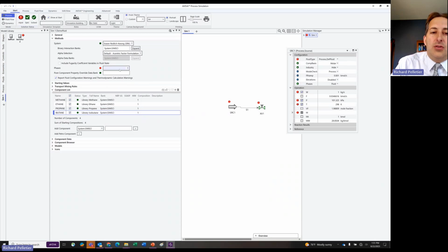So you have to be careful what you pick, to make sure that it is all encompassing of what you might have within your system. For these more complex ones, it adds a third phase that gets considered. For VLLE, you have a secondary liquid phase, which could be any other component that's immiscible in the primary liquid, right? So you could have ethanol, water, type of thing that creates maybe two separate liquid phases. That's potentially something that could happen, right?